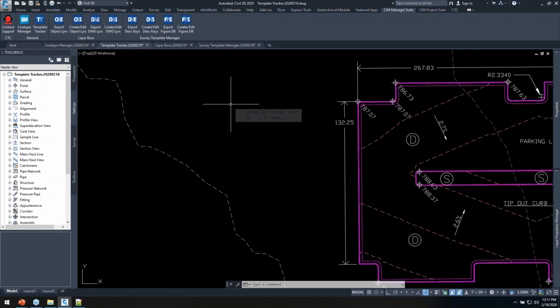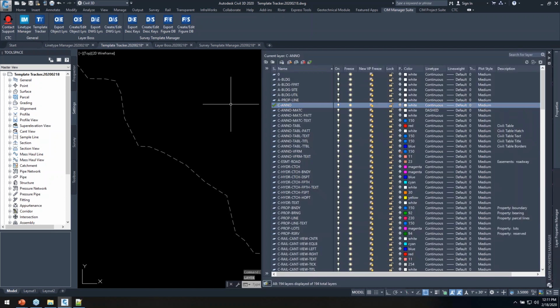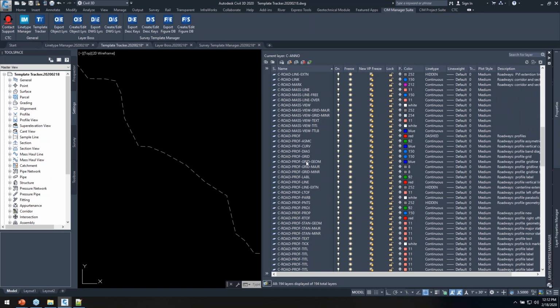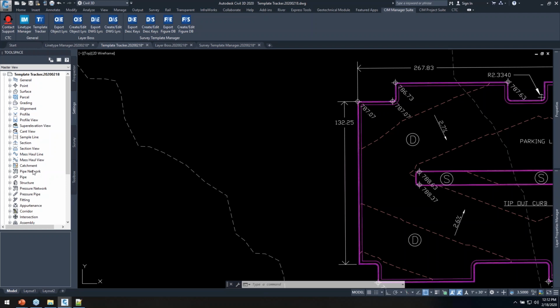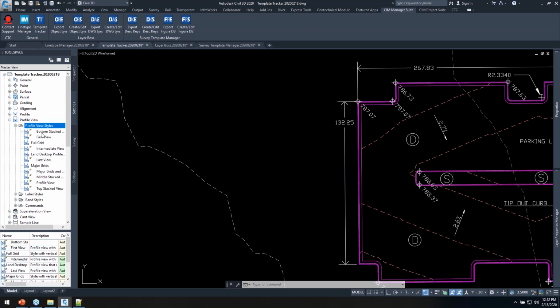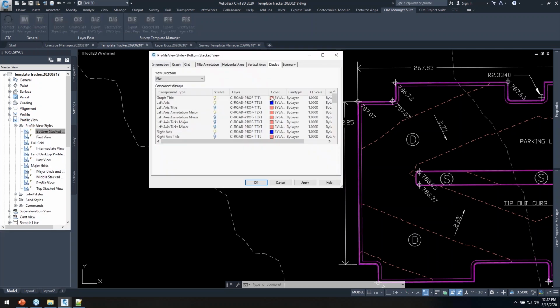When building out Civil 3D templates, editing them, overhauling them, we're of course dealing with links between all these things, like layers embedded in styles. Let's take an example. Let's look at our profile view styles. These are large, complicated styles, and embedded in here are all sorts of layers. And as we're refining, changing, updating, or building a new template in the first place, we need to be managing this stuff.